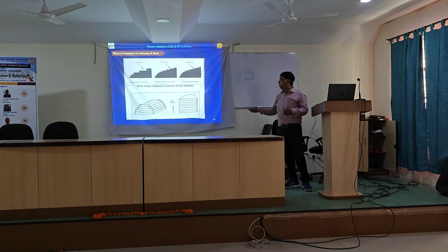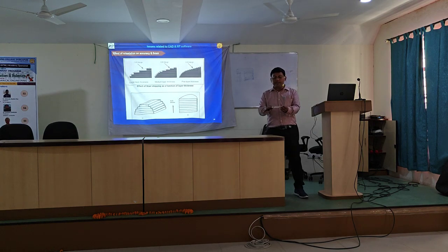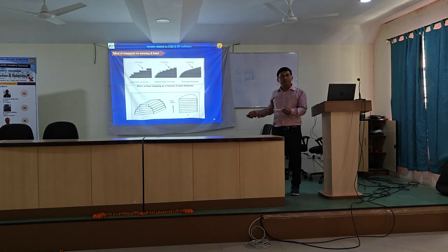I have taken a very simple example to show you the concept. If you would like to create a half cylinder by an additive manufacturing process, and you orient like this and do the slicing, in each slice your cross section is a rectangle, but the width is different. Length is the same, height is obviously the same, equal to the layer thickness.